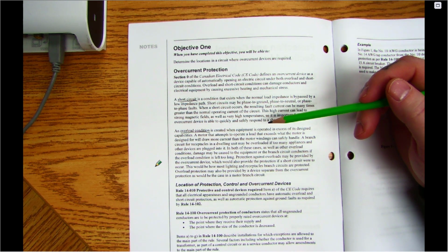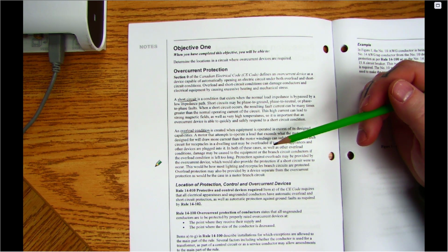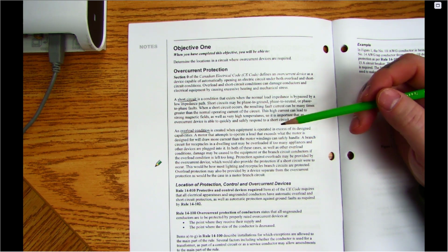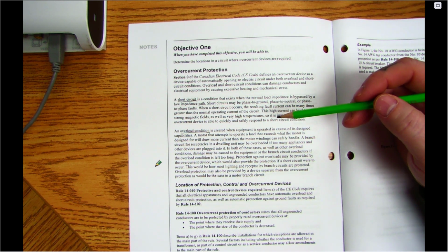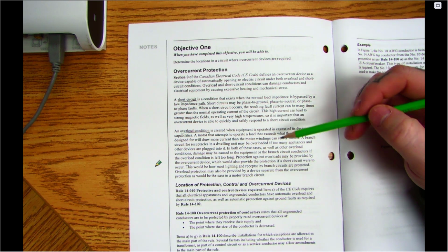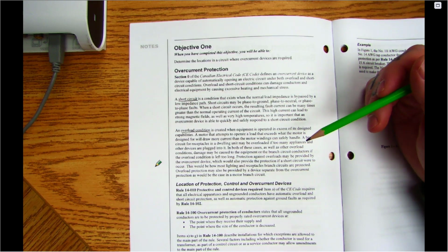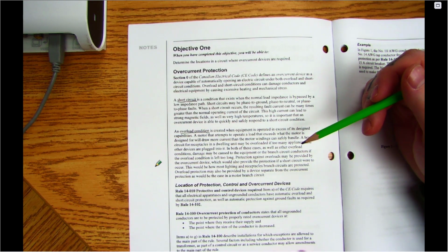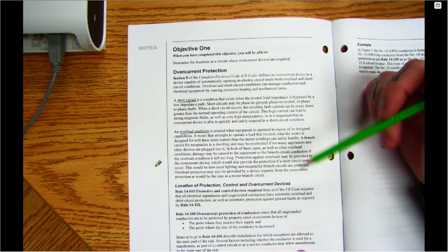So that excess of current draw, because it's either being asked to pull too much through the design circuit, or potentially it's undersized for the actual piece of equipment. You'll see a trip due to overload, which basically is I'm drawing current for too long, heats up the cable, and then usually, in the case of a breaker, will move a bimetal strip and then trip due to overload as well. So those are the two things we have to worry about: short circuit and overload, and the terms.